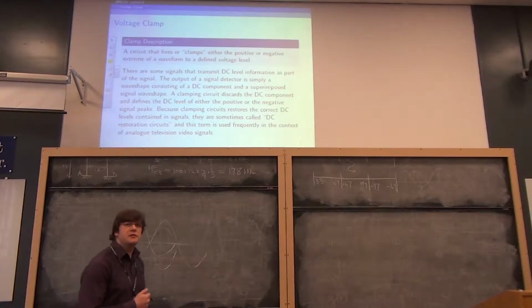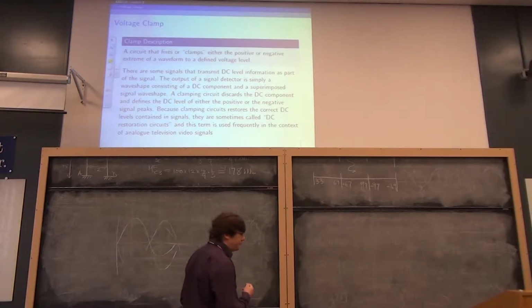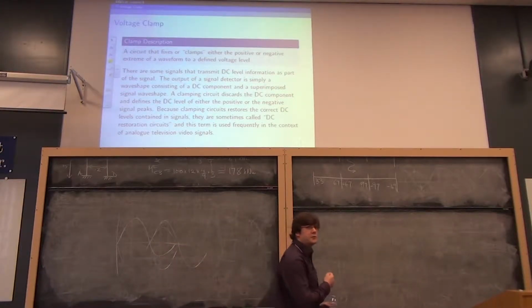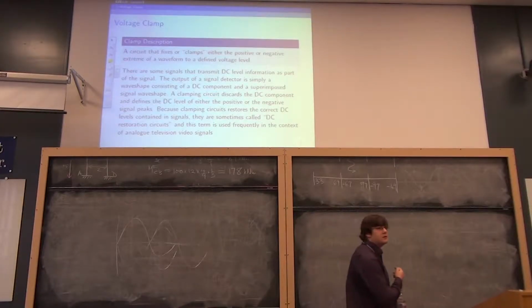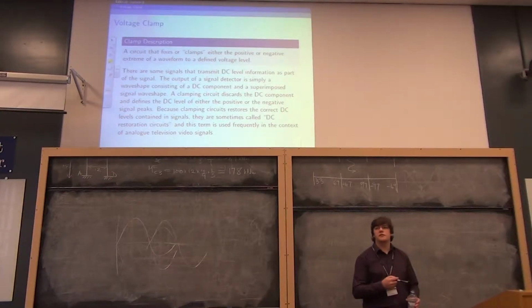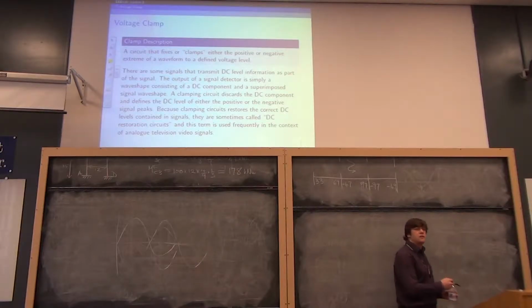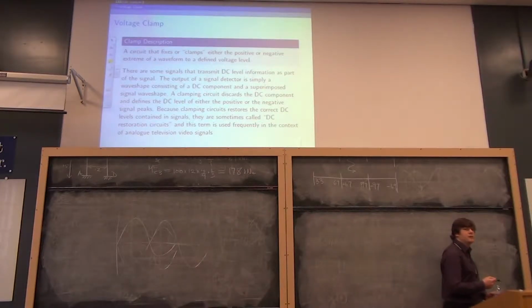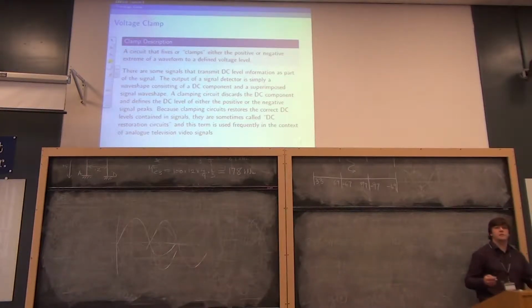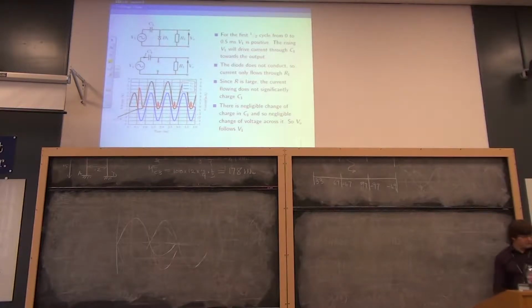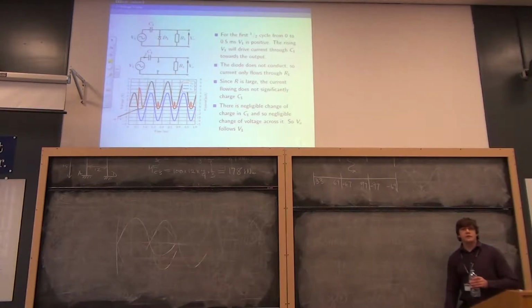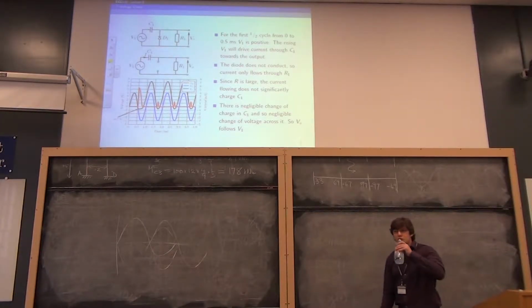And when we transmit the signal, the DC is changed because the modulated carrier has no DC component, and the peak detector recovers the signal and gives it some DC value. So our DC component's been buggered with, and we've got to get it back. So we can use a clamp circuit for this sort of thing. It's secretly just a rearrangement of the same three components.